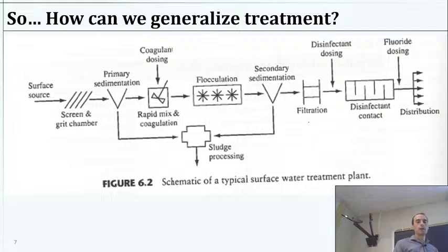Perhaps just simply direct filtration. So we'll talk about things like a gravity-fed membrane system that perhaps you can just hoist a bucket of water, hang it on something, and then have a tube come down, and a meter or two of water height is enough pressure to push water through a membrane, and you can get tens of liters a day that way. That requires a fair bit of work, but you can get membranes that don't require much maintenance. So that's quite possible.